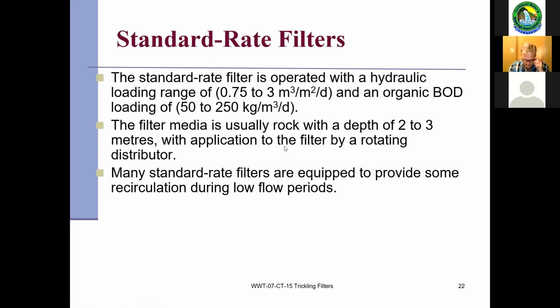If you think of it in your system, your diurnal flows are typically higher in the morning, then they slow down a bit, and then in the early evening they pick up again as everybody gets home, and then overnight they typically slow down. So a lot of these standard rate filters will have some kind of recirculation, so we can continue to feed the microorganisms in that filter media in lower flows.